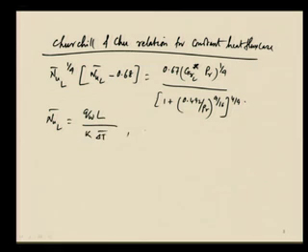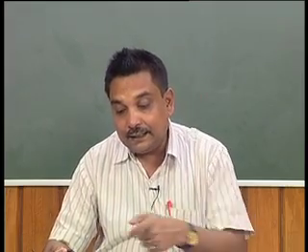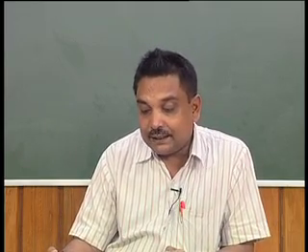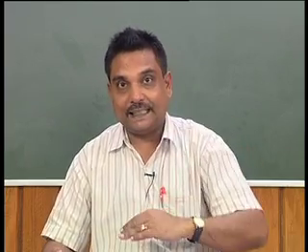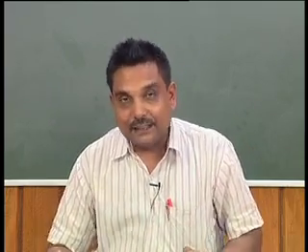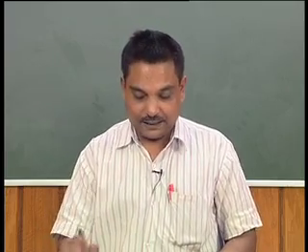So, now delta T bar is being defined this way. It is actually T_W at L x equal to L by 2 minus T infinity. Delta T, as we understand, will go on changing as we go along the plate, and here this delta T is taken at a very particular condition, when the wall temperature is at the center of the plate, that means lengthwise it is at the middle of the plate. Okay. So, that is delta T.